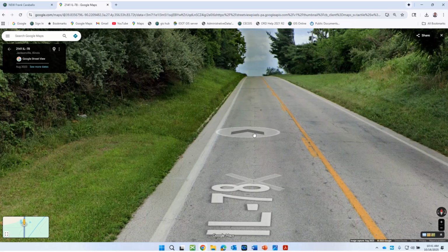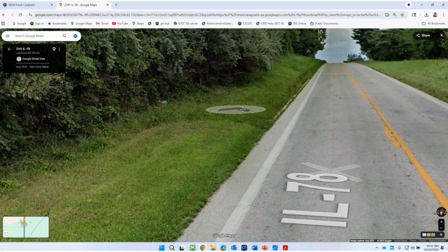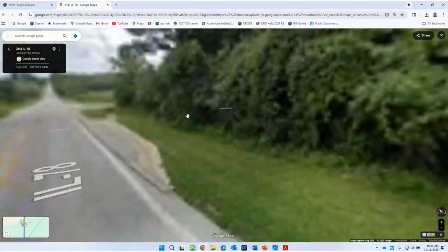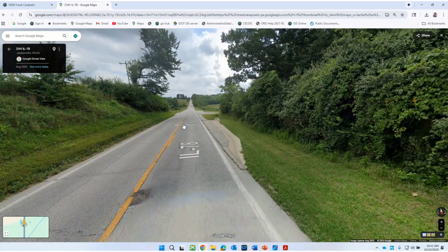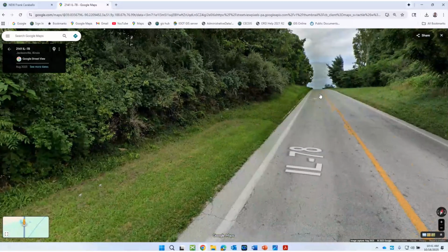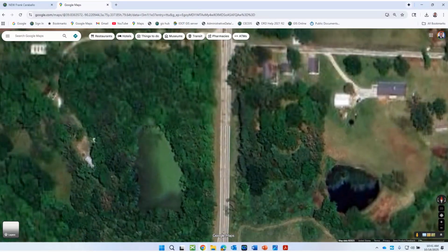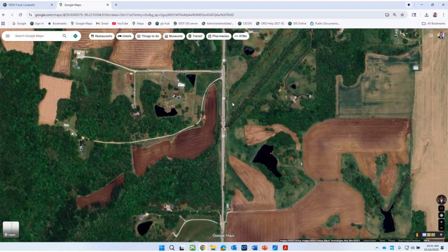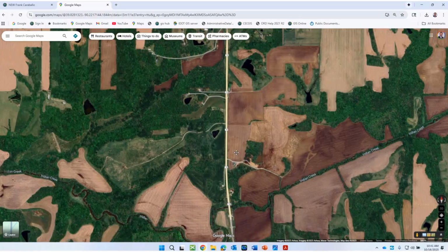And so we actually removed that widening back to where you can see that crack running down the middle, widened the pavement, added the type A gutter. And then again, this was from a previous job, I believe from that bridge job. So in this case here, we did something similar to what you see, where we're just going to tie into that existing gutter outlet. And really that's, like I said, just kind of the same thing throughout.